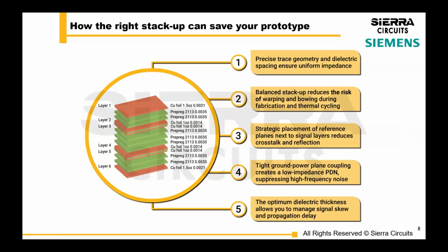So, when you're designing a stack up, and you have an idea of the HDI portion, and an idea of the signal integrity that you want to achieve, you also have to create a mechanically good stack up, which basically means you don't want to risk warping or any bending or flexing during the PCB process or even in the assembly process.